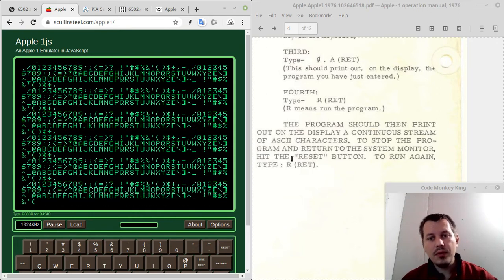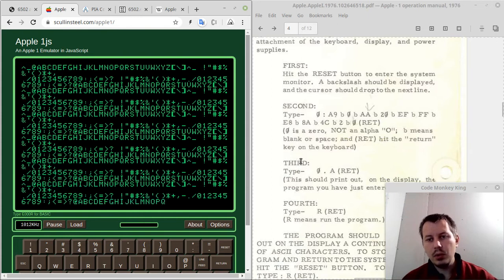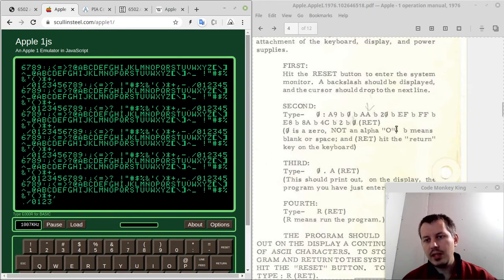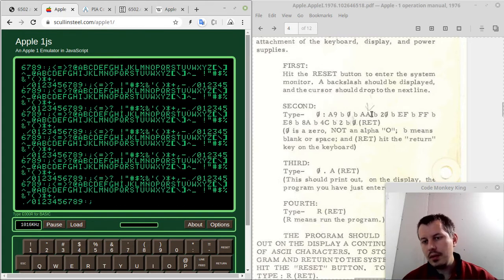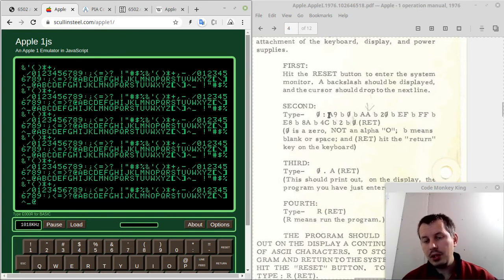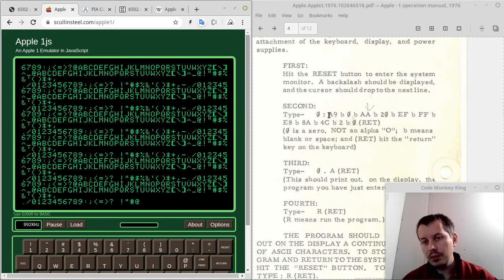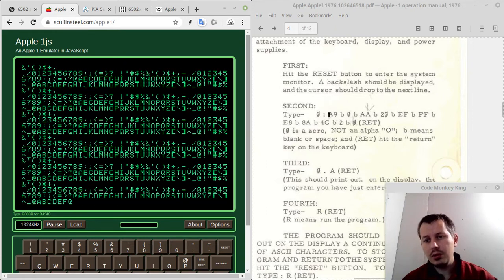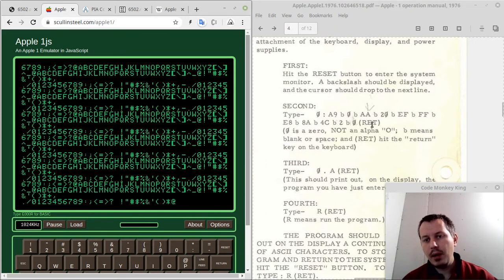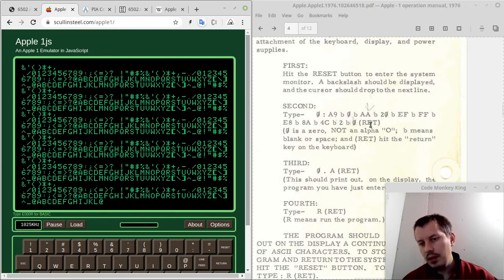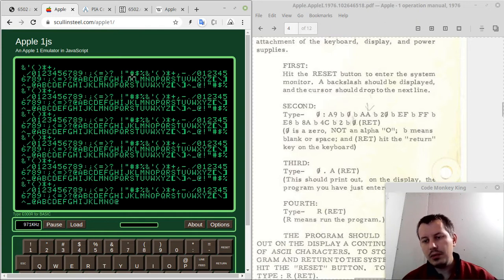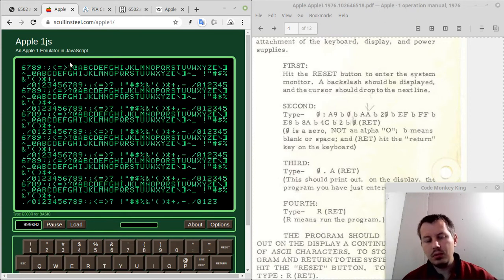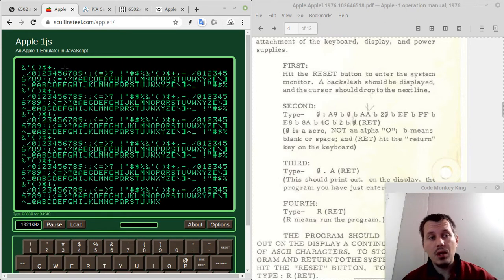All right, guys. So this was cool, right? So this works, but we have no idea how exactly this works. And a little spoiler ahead. I already know that these are obviously the machine codes for the 6502 processor, which Apple One is based on. So let's try to type these bytes into a disassembler, and then see the 6502 assembly language mnemonics to have a better idea of how this works.